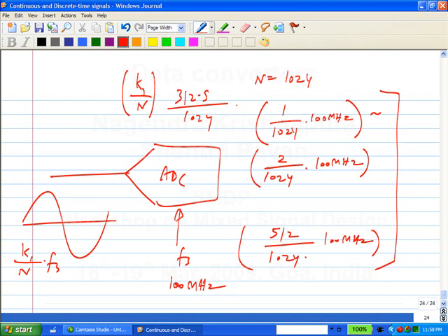In fact, this is a simple thing but not very well known, because this is more signal processing related, it's not very well known among circuit designers. So you see a lot of times the FFTs which look like this, which have lots of leakage, and it looks as though there is some quote unquote noise, but it's not noise, it's simply sampling which is done improperly. So whenever you are simulating or measuring, you will have the option of choosing the frequencies, and you have to choose it like this.